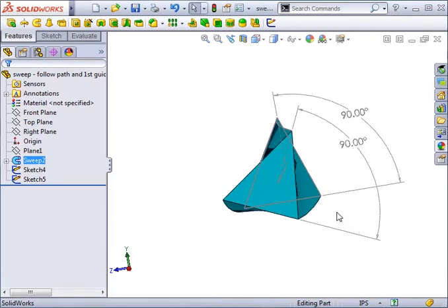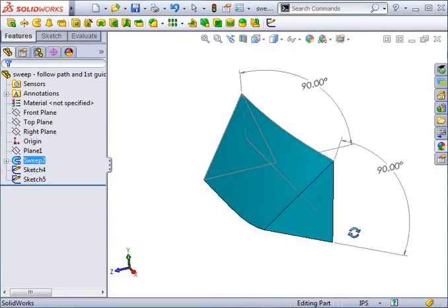This may not seem very important to you at the moment, but you would be surprised at how many times users will add guide curve after guide curve in an attempt to end with this exact result, simply because they don't understand how the setting works. If you understand the principle behind the setting, the same thing applies to Follow First and Second Guide Curves, except this line is defined by connecting the first guide curve to a second guide curve instead of the path.